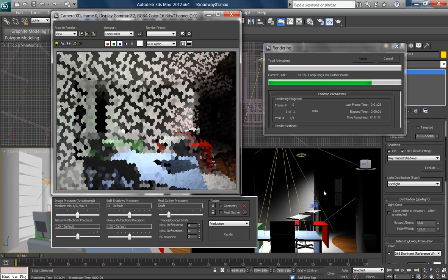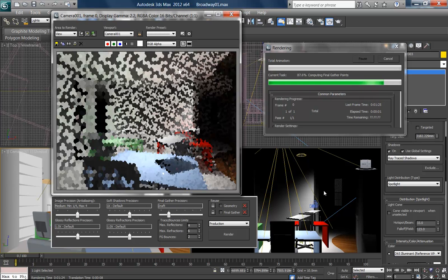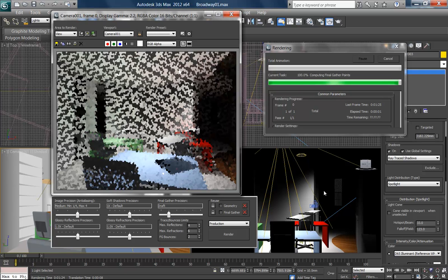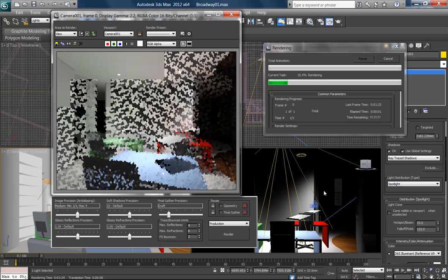But you can see, hopefully, much more controlled than the lighting in Revit. In Revit, it was everywhere and not really targeted very well, and also the colour would have been much more difficult to control because you've got lights interacting with each other and you don't know what's doing what. But when you can target the lights and manage them like this, then you control the final output, and you're not hitting render and hoping to get a good product. You are controlling the output, which takes a lot of experience to realise. Up until now, essentially what you have probably been doing is hitting and hoping that you get the output you're after, but you're not knowing how you get there. It takes years really to get to that point.